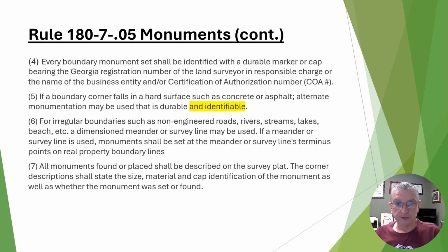I'd rather put calls down the stream, down the middle of the swamp, wherever I think, so we can compute an area and everybody understands that work product, and we denote it as, center line of stream is property line. That puts everybody on notice that it's a riparian boundary. It might move next week.